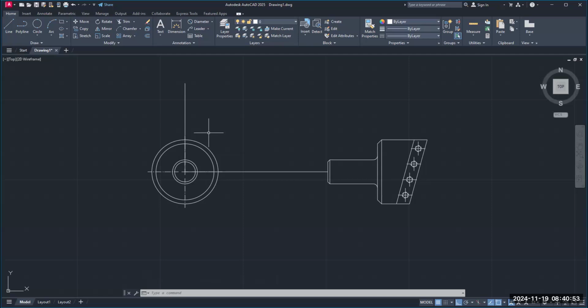Now, as you can see in my left side view, I have a dimension of 0.69. On the right side view, by the way, the left side view is a mirror image of the right side view with the exception of the line types. You have to change your line types to agree. So this is a mirror image, so it's going to be the opposite of the right side view.